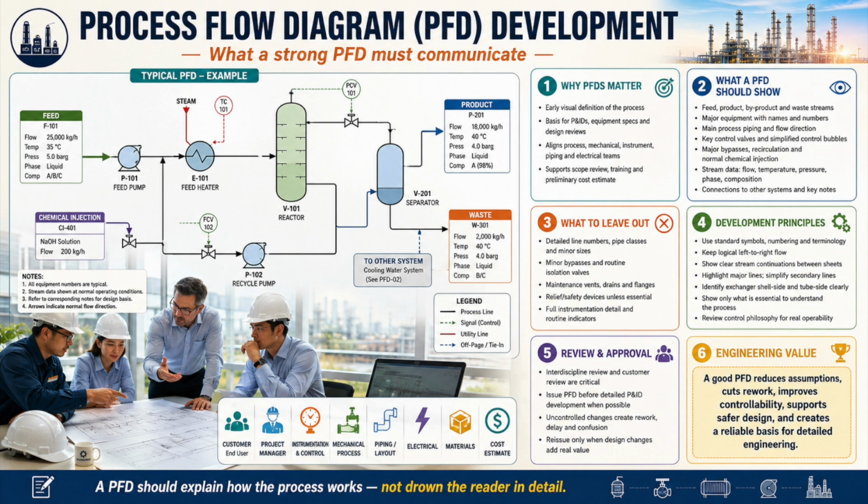When the process cannot be shown clearly on one sheet, divide it into logical sections. Do not divide drawings merely to satisfy arbitrary sheet density. Each sheet should represent a coherent process function. Every cross-sheet continuation must be unmistakable. Use a boxed continuation arrow showing the source or destination drawing number.